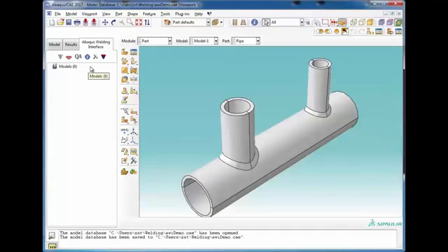When we create a model in the welding interface, essentially we do a lot of work inside CAE before we do anything inside the AWI. The first thing we would do is create a part that's going to have some welds in it. We would generate the geometry and the mesh and create the areas where the weld beads are. Once that's done, the next thing would be to create the material properties that are going to be used inside Abaqus CAE.